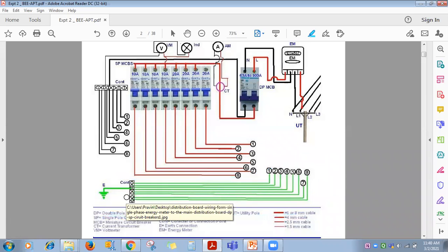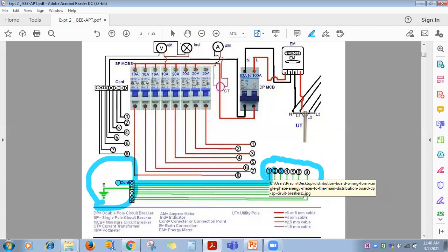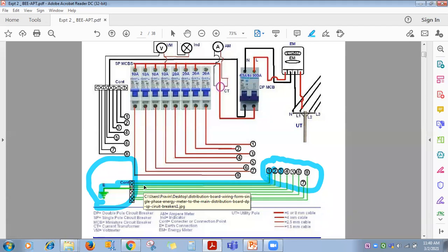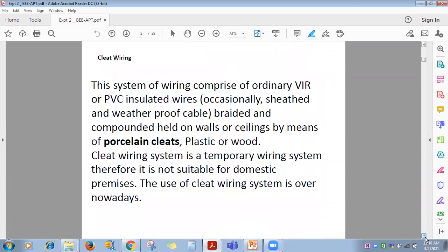Okay, so this earthing arrangement is done under the ground. So all these are sockets. All of you know sockets. In a socket, of the lower 2 terminals, one is live phase, another is neutral, and the upper one with more diameter is the earthing. So these are nothing but earthing terminals of the socket. Okay, you can consider this, and from here the earthing wire is connected to the ground earthing arrangement. Earthing also in detail we are going to see in today's experiment.